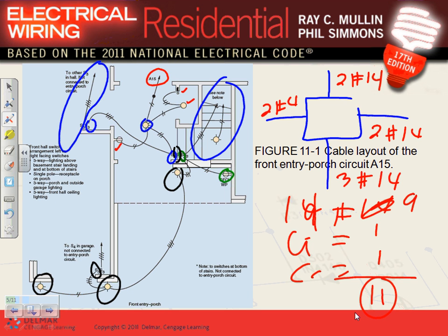Any question, guys? Good point, though. Good observation. I just went through the standard sizes and the code. And you couldn't find it? The metallic ones? You have a box here, plastic. These would most likely be plastic. I have 10 number 14. This can handle 10 number 14, the standard one. Okay, 10 number 14. So we're short one.